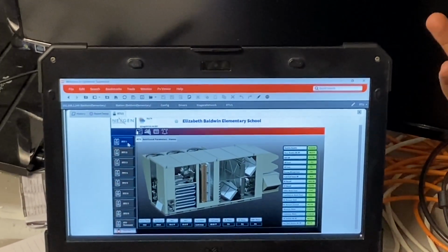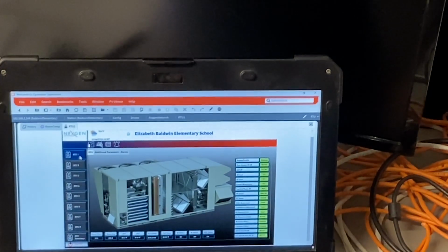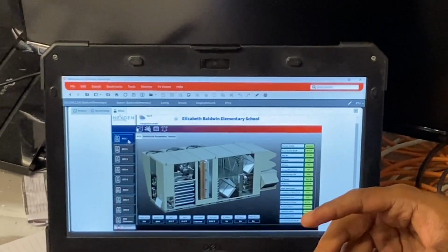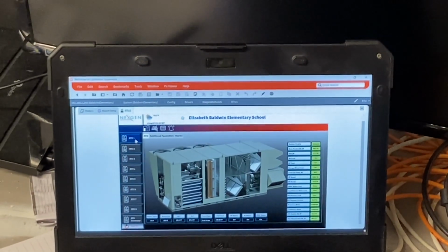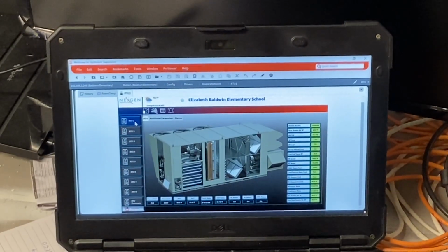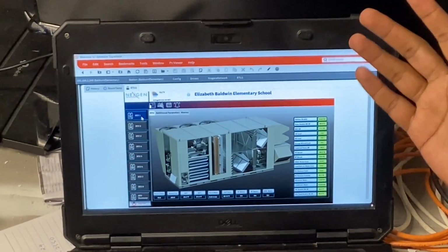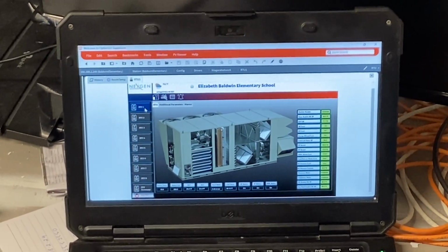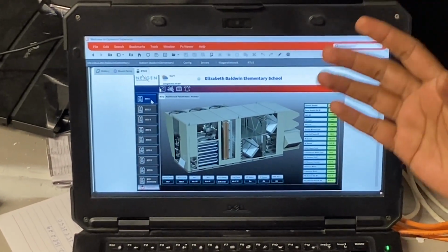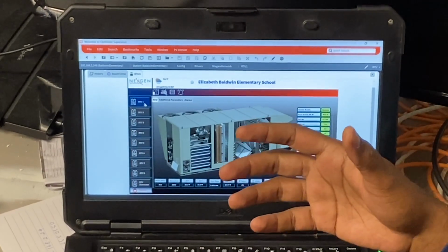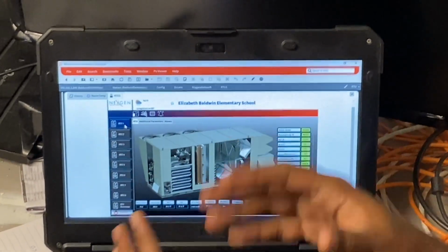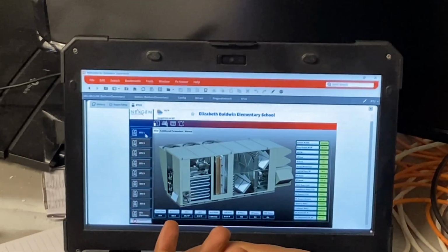Probably the load is not there, but let's say during the occupied time, after the VAV has taken over, the average space temperature is way below 68, and you can adjust that set point. Your radiant panels are your first stage of heating. If your radiant panels couldn't keep up the heat, then the morning warm up is going to kick in as a second stage heat.